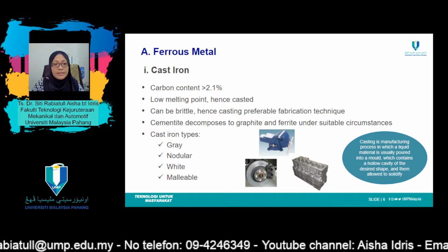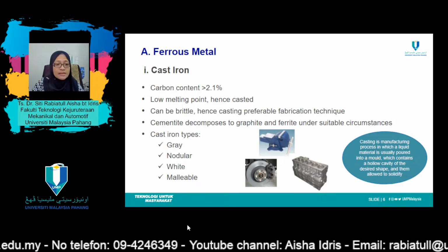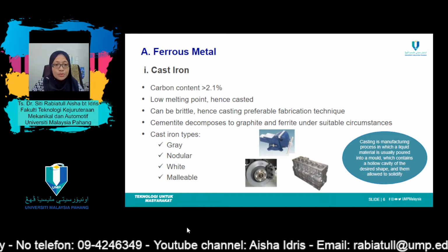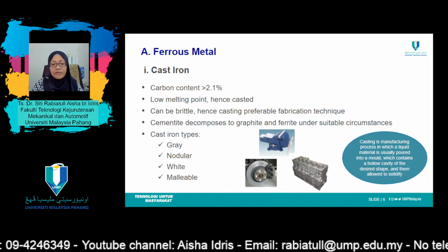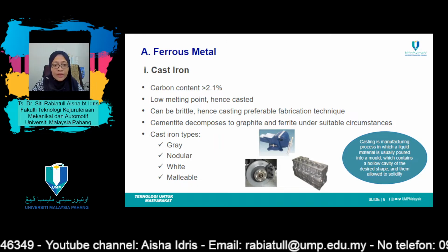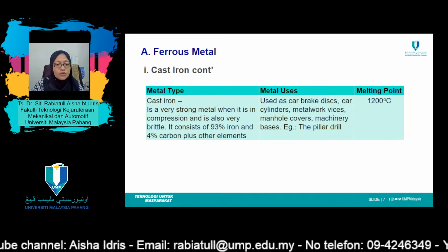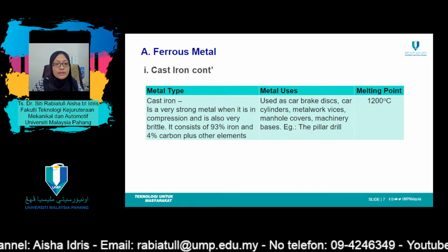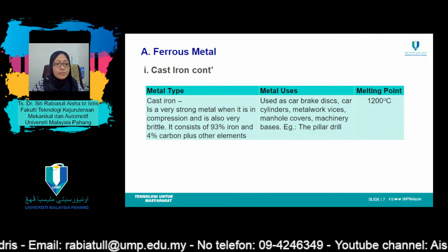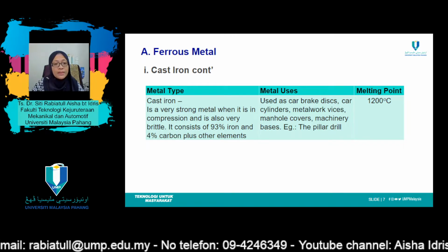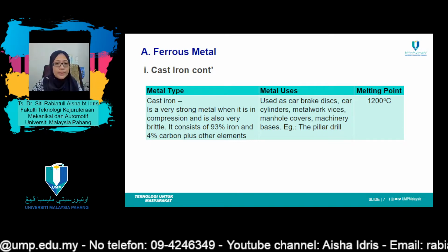Cementite is a metastable compound, and under some circumstances, it can be made to decompose to form alpha ferrite and graphite. The tendency to form graphite is regulated by the composition and rate of cooling. Graphite formation is promoted by the presence of silicon in concentration greater than 1 weight%.